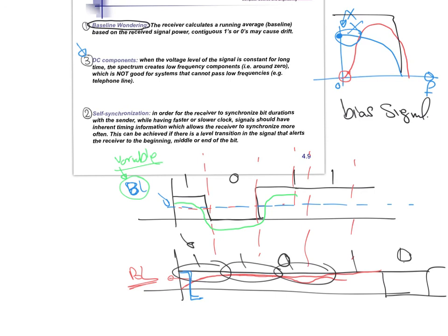So as we said, for example, our voice has a bandwidth of 4 kilohertz. Right? We said that our voice has 4 kilohertz. So we need to use a low pass filter with a bandwidth of 4 kilohertz. However, if you do this, you discover that any voice components below 200 hertz are not easily heard, or not easily detectable.